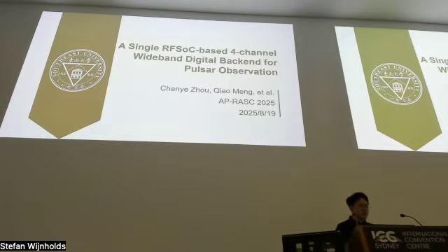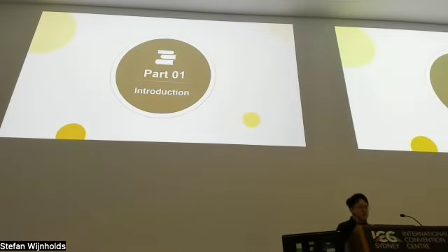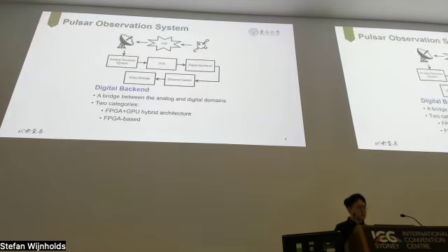My presentation is about a single-chip RFSoC-based 4-channel wideband digital backend for pulsar observation. We'll have the following parts. The first part is a brief introduction. This is a typical pulsar observation system, and the digital backend serves as a bridge between the analog and digital domains. There are mainly two categories. One is FPGA plus GPU hybrid architecture, and another one is FPGA based.